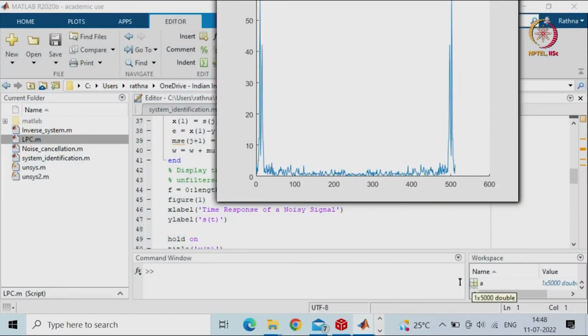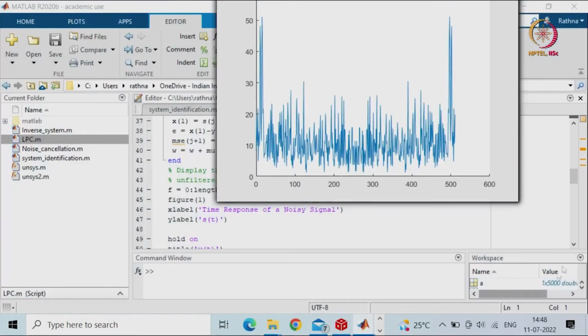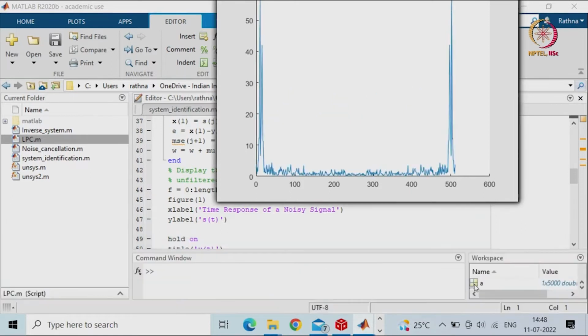And then figure 6 is the sine wave, and according to this we have done 1000 iterations. You will be seeing that we are able to achieve the error signal coming down, and the sine wave is seen at the output; it has adapted. This also shows the error in the frequency domain, where the noise is much reduced compared to the previous one, which has been filtered out.